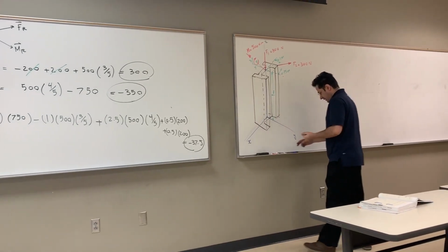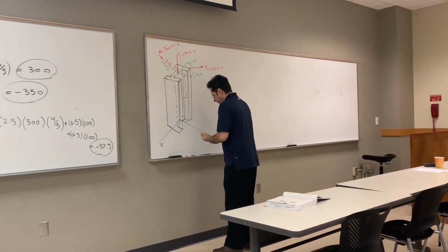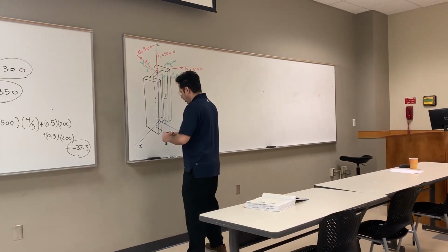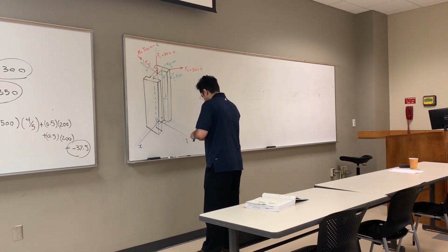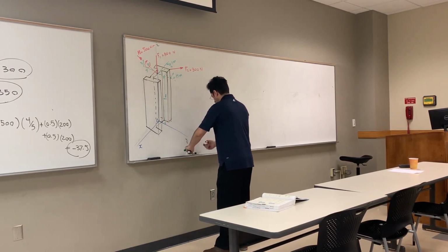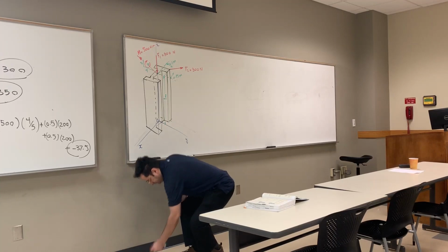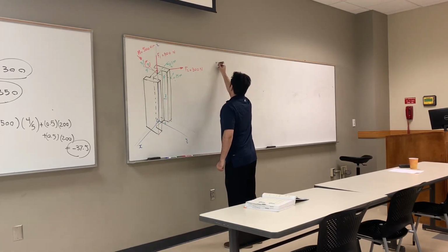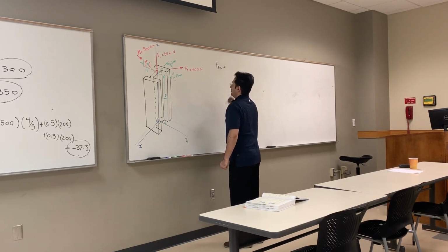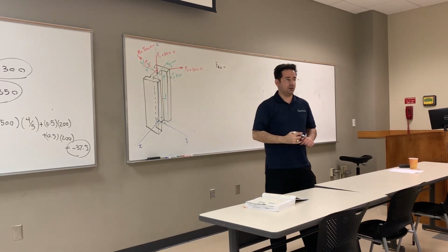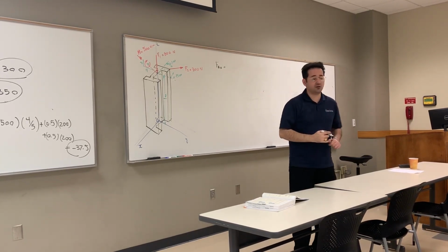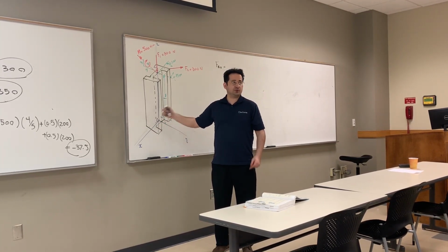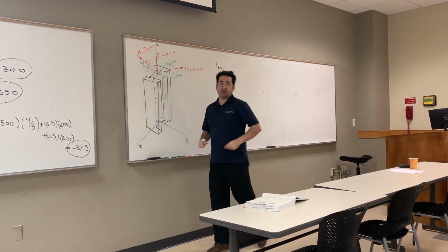So I want to replace this system force and moment with just one single force and one single moment at point O, and this is my point O. Solution. Go ahead and solve it. So I write F resultant x component is equal to sum of all the x component. So you find the resultant force, you find the resultant moment with respect to O, then you put force, resultant moment vector 2, and you get rid of the rest of it. This is the procedure.